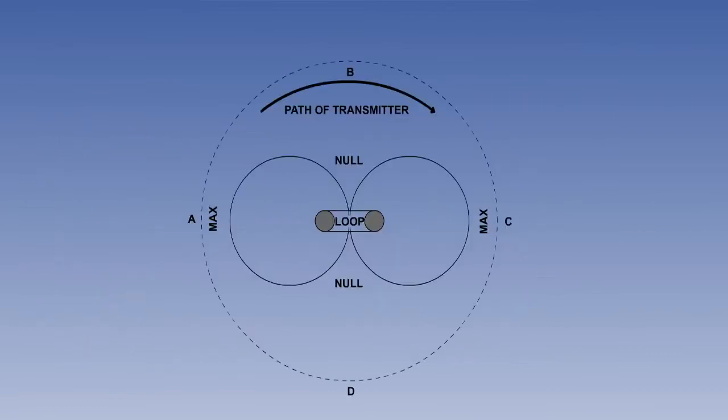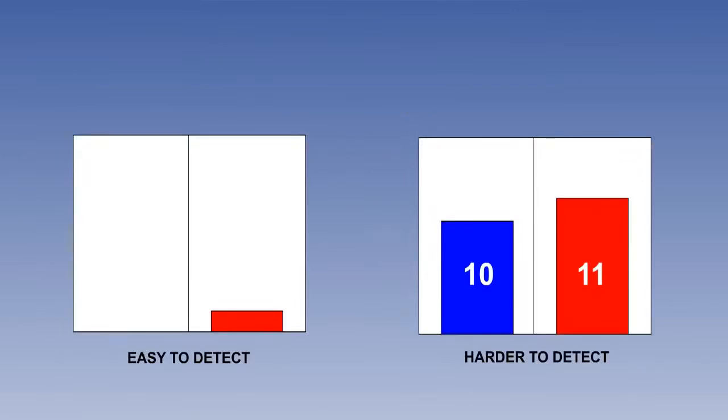There are two positions at which there is no difference between the strength of signal received by the two vertical elements of the antenna, at 90 and 270 degrees on the sine wave. The signal difference is said to be zero or null, shown at positions B and D. The null point is chosen over any other phase as a datum point, because small angular movements from 0 produce a greater electrical response, and are therefore more detectable than an increase to an existing response.